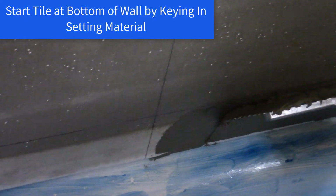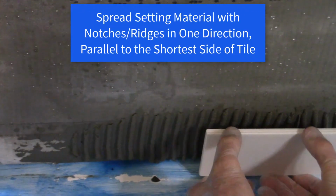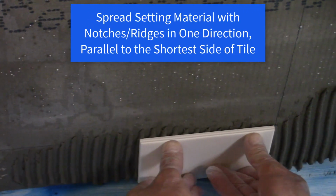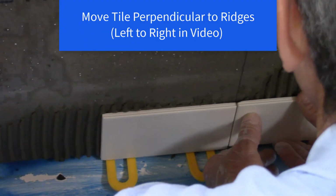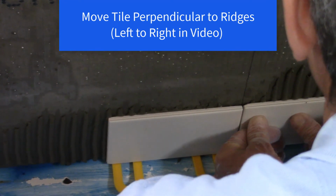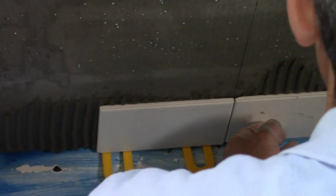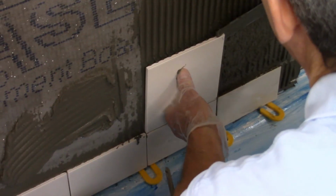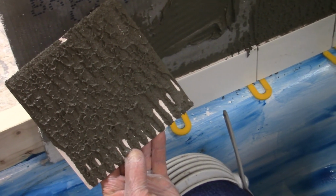Start tiling at the bottom of the wall by keying in or burning in the setting material into the substrate. Remember to allow room for thickness of the floor tile setting material, plus a 1/4 inch expansion joint. Spread the setting material so that the notches or ridges are all in one direction, parallel to the shortest side of the tile. Move the tile in a perpendicular direction to the ridges, causing them to collapse, which pushes out the otherwise trapped air, yielding maximum coverage. The NTCA Trowel and Air video shows this technique, providing improved mortar coverage.